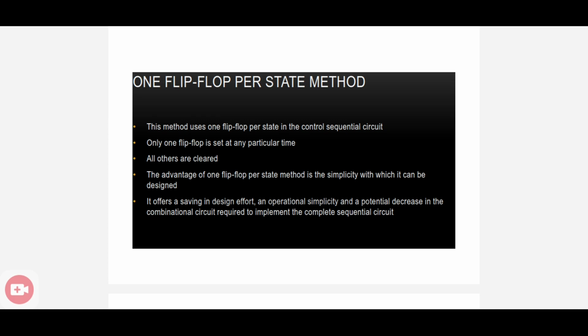Clear? And what are the advantages of one flip-flop per state method? Main advantages, it is its operational simplicity. Also, it has a potential to decrease in the combinational circuit required to implement the complete sequential circuit. So this is the main advantage.